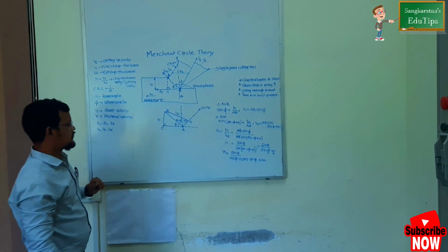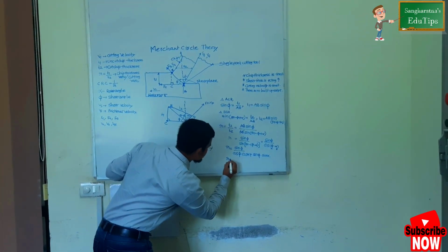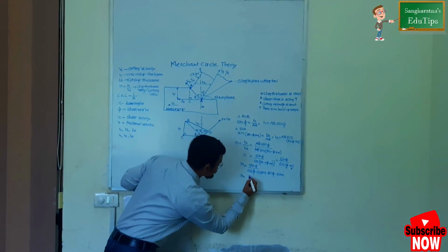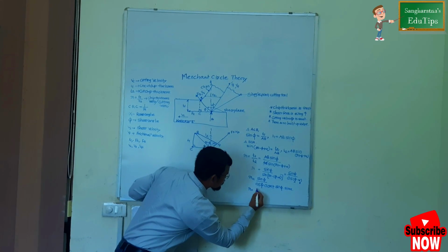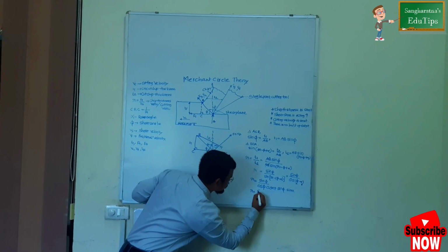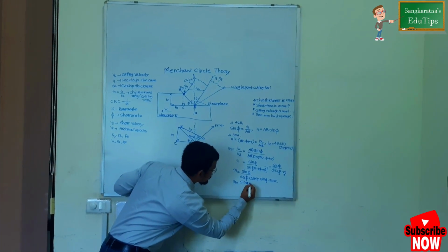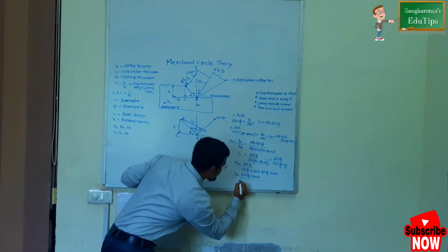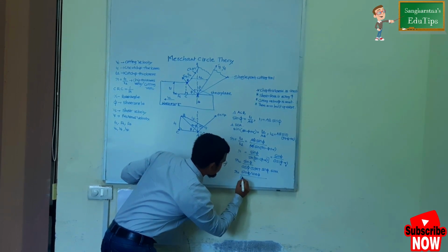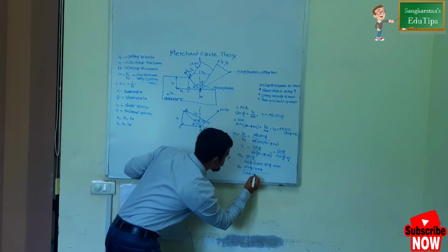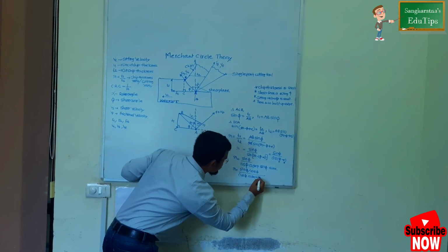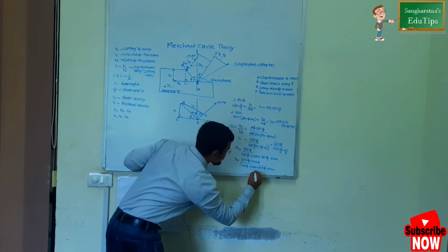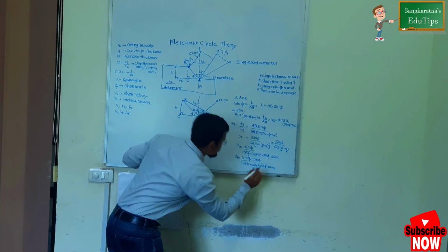So once we got this equation, in the next step, to determine the shear angle phi, we are calculating some equations. I am simply dividing with the help of cos phi: cos phi in the numerator, divided by cos phi. Similarly, I am dividing this whole equation, cos of phi into cos alpha plus sine of phi into sine of alpha, divided by cos of phi, right?